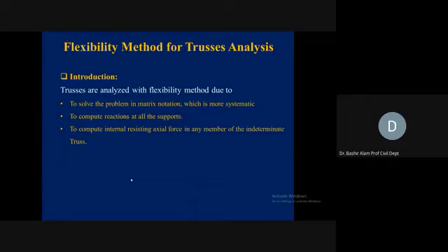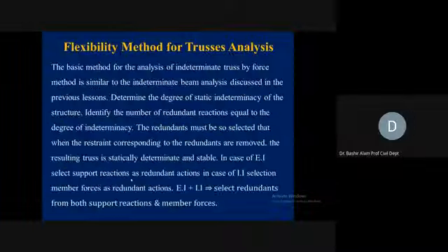Now, solution of the simultaneous equation, if we go by the conventional method, is very difficult. So first we write them in the matrix notation form, and then we solve the matrices. And especially this is easy now with the help of the computer. We can find out the support reactions by using this, and we can find out all the internal resisting axial forces with the help of this method.